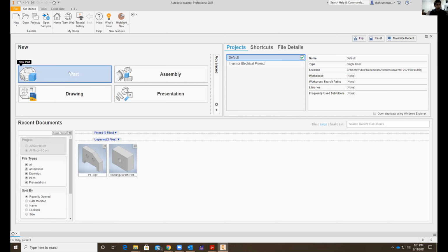After making the parts, what do we do? The assembly, right? For assembly purposes, we use the assembly module. The part module is used for making parts. The assembly module is used for assembling different parts. So the shaft will be inserted inside the wheel. The cabin will be on top of the chassis. The door will be at the side. All those assembly things can be done with the assembly module.